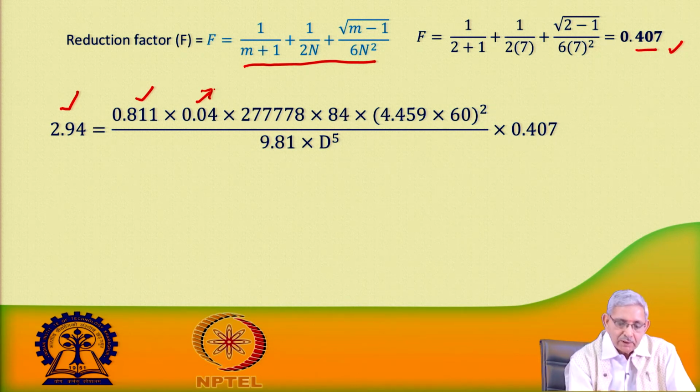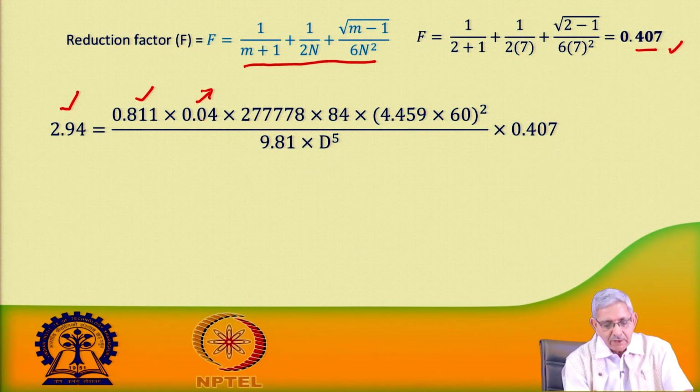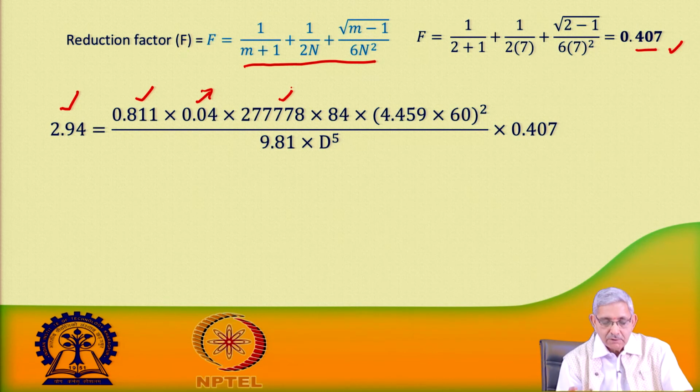F is assumed or available to us, so we are not computing it using the Reynolds equation or the Moody diagram; we are directly giving you this value. One has to estimate it from the Moody diagram. So this F is known to us, that is 0.004, then small c using the SI units.